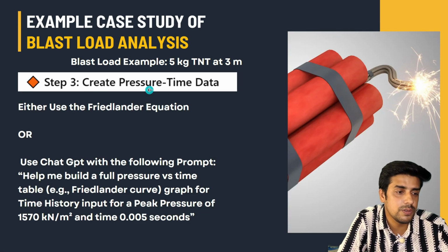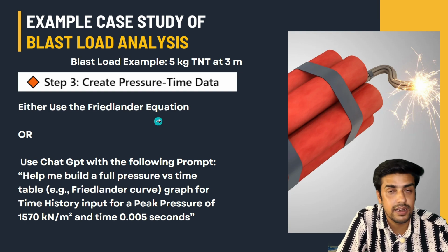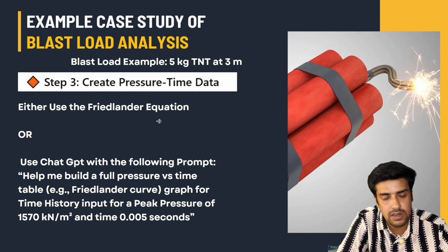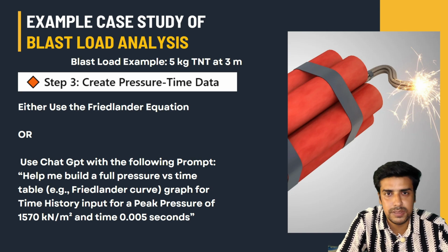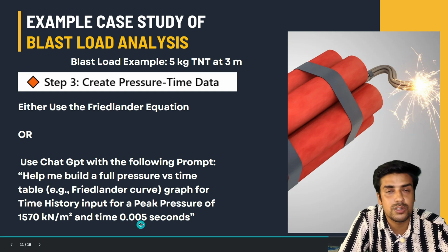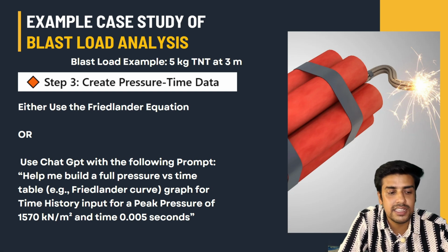Now what we have to do is create a pressure time data. Onto the y-axis we are going to have pressure, and onto the x-axis we are going to have time. Now we have the pressure, that is 1571, but we don't have the time right now. So it is based on your experience or on research what time you are going to take. Generally, the blast loads are of very short duration. I am taking the time 0.005 seconds,